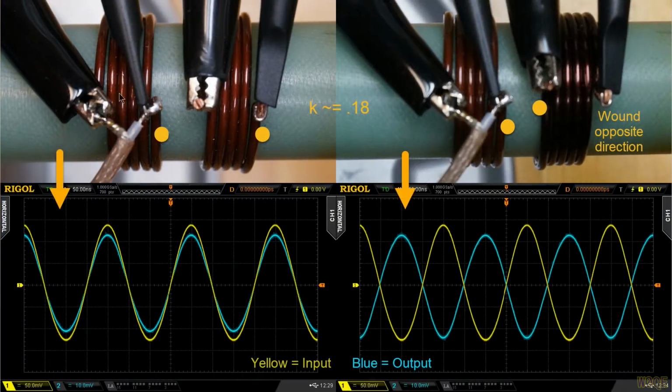Shown here are two coils, 5 turns each, wound fairly close together, and they're aligned with each other, and they're both wound in the same direction. If we start right here, we see the winding going this way. We start right here, we see the winding going this way. 5 turns. This would produce phase dots that would be in this orientation like this. Or you could put the dots on this side and this side, and that would be the same too.